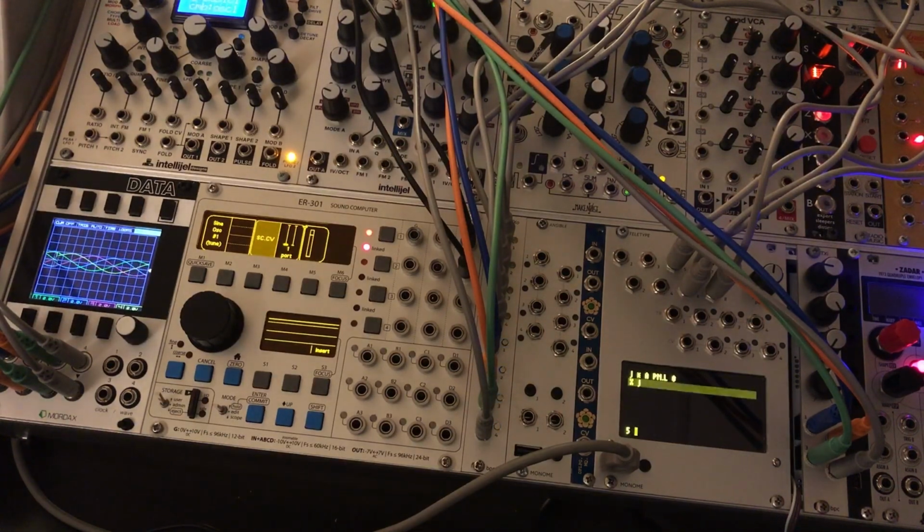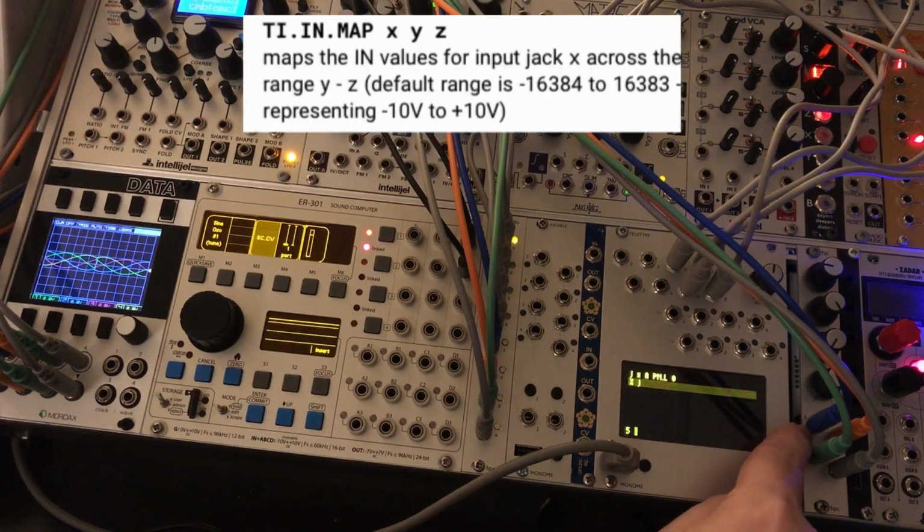All right, the next thing we want to do, so we've got this LFO, the first one, coming into input 1 over here. And just like we mapped ranges for these parameter knobs, I want to map a range here. Normally, as we vary from minus 10 to 10 volts, it would have a range of minus 16,383 to positive 16,383. I really just want this to map from 0 to our total number of notes, which right now is 20. So let's set that up.